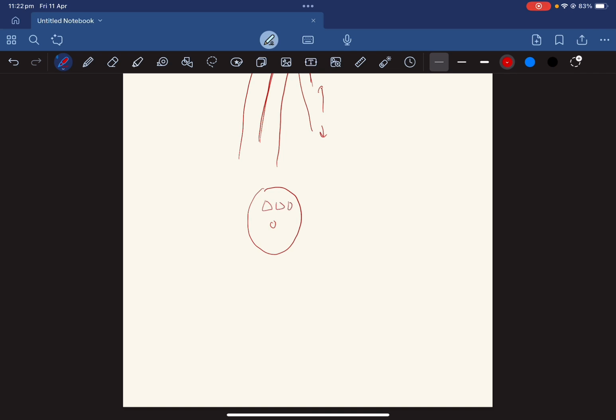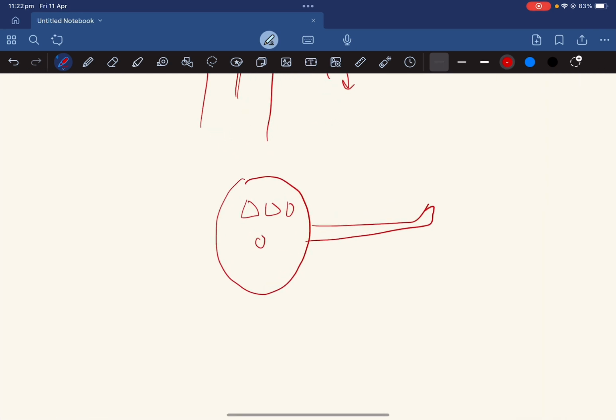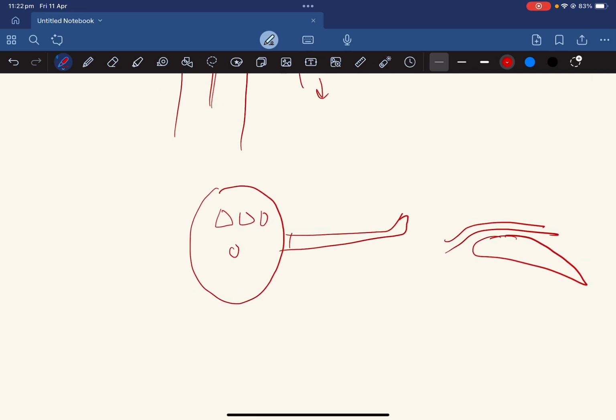Really sorry for my drawing. So this is your wing. As you know, when you see from the side, this is your aerofoil. Your air is accelerated over here, right, on the aerofoil. So basically, the air is quite fast over here, and the air is comparatively slower over here. So when these meet together, they give a type of drag that is called interference drag. I hope it makes sense to you.